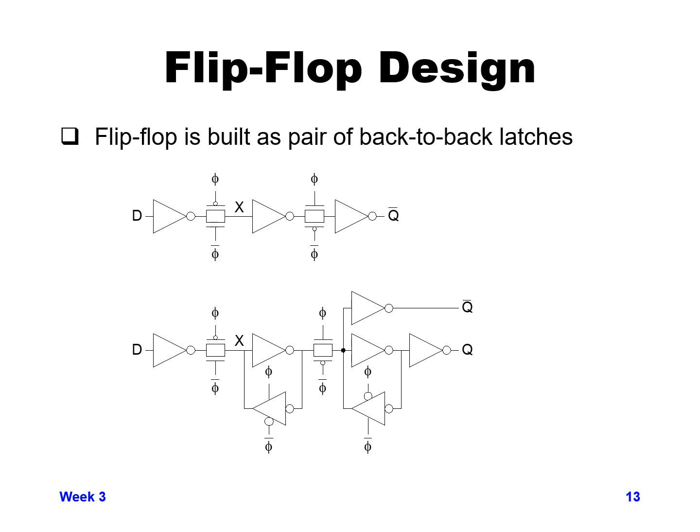When the clock goes low, the slave closes and continues to hold the value of X, and the master opens. It allows a new value of X to come in, but since the slave isn't looking anymore, the slave holds the old value of X. So again, a flip-flop will only change value when the clock goes from low to high. The master will push its value to the slave, and then that value will be held until the next time the clock goes from low to high.